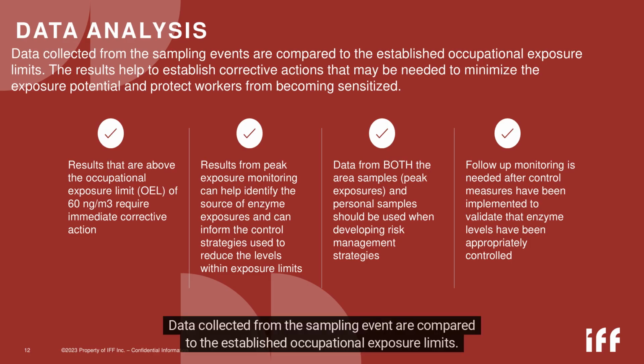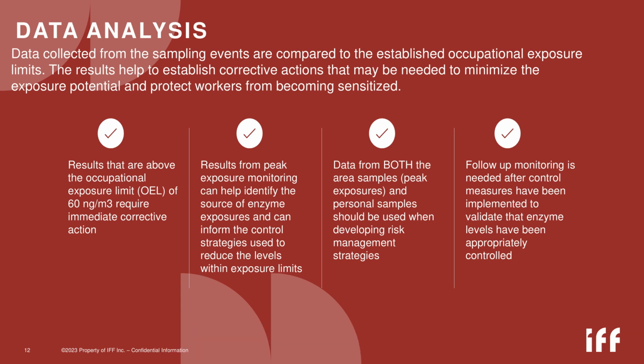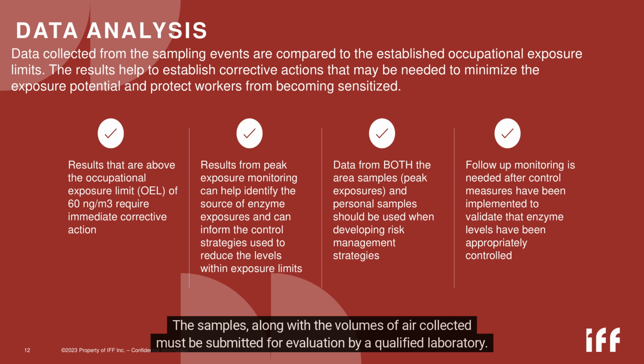Data collected from the sampling event are compared to the established occupational exposure limits. The results help to establish corrective actions that may be needed to minimize the exposure potential and protect workers from being sensitized. The samples, along with the volumes of air collected, must be submitted for evaluation by a qualified laboratory.